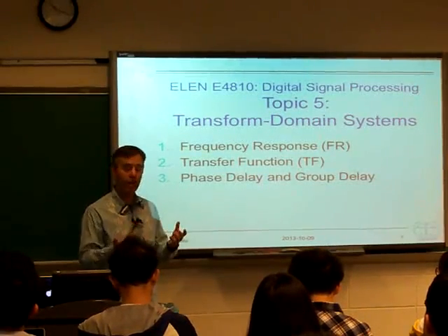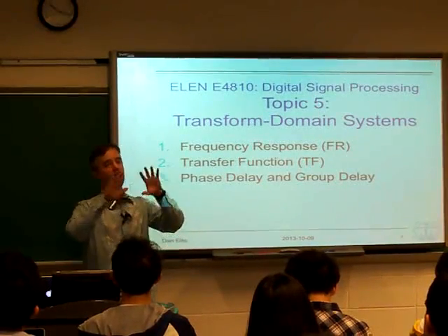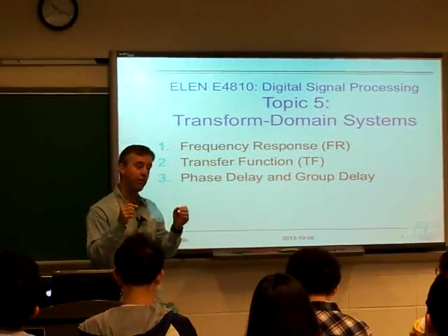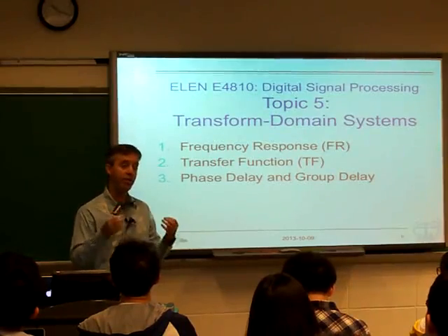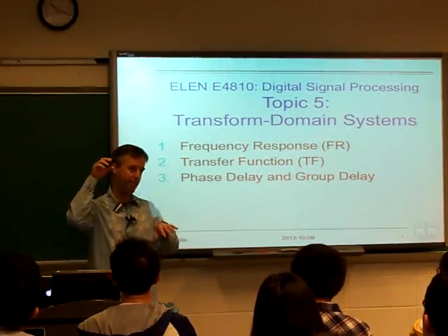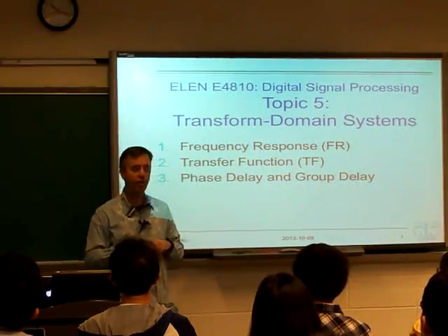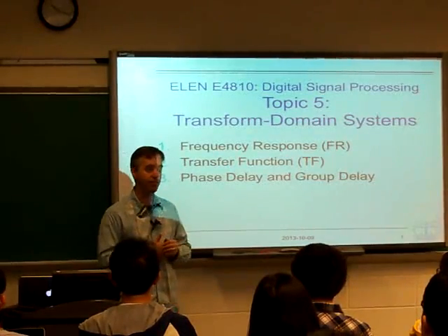The Fourier transform, the part we're interested in, is this unit circle, but the behavior of what's going to happen on that unit circle is determined by the roots. If we happen to have a closed form of a rational polynomial, the roots of that rational polynomial, the poles and zeros, are maxima and minima of this surface, and it's where the unit circle slices that surface that gives us the Fourier transform.